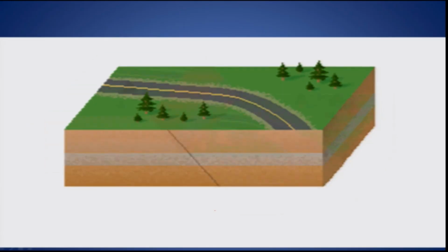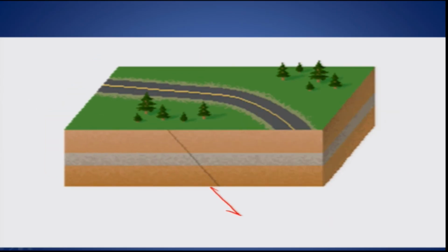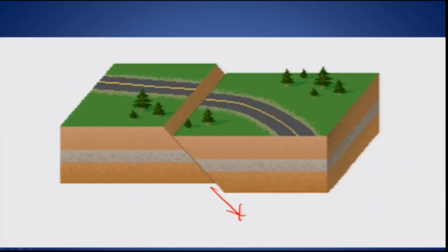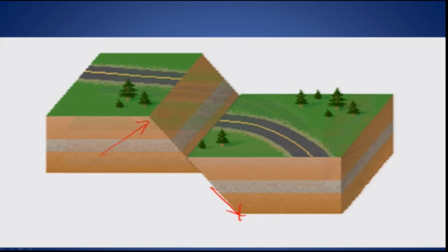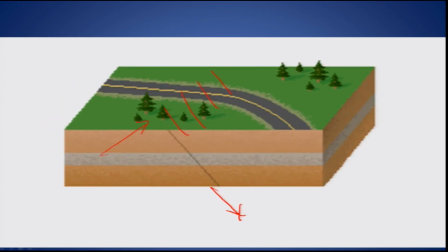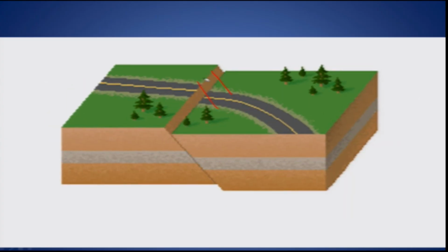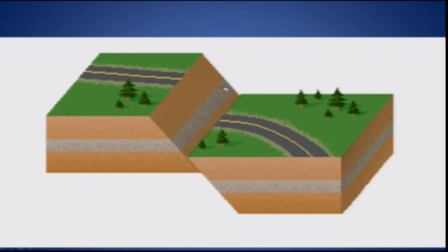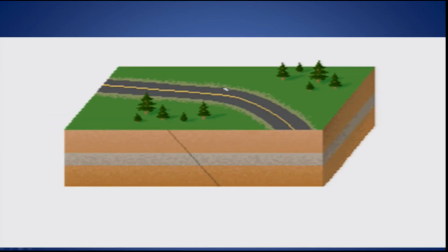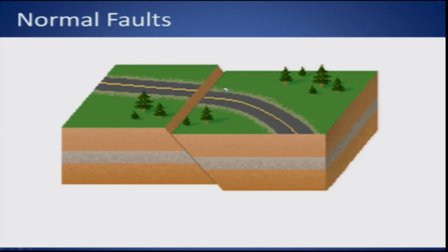Now this one is again a fault plane along which the movement has occurred, the block has moved down, and the strike of the fault is over here like this. This one is the strike. And what you are looking at, which is coming up, is the fault scarp. Now this is a type of dip slip fault, because the movement is taking place along the dip component, and one block is moving down relative to the other. We are doing stretching, hence we term this a normal fault.